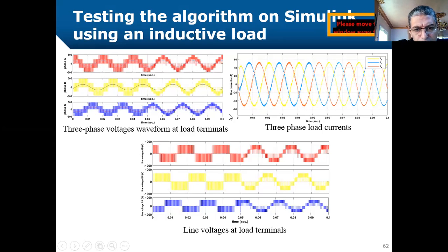second, or 0.005 second, we drive it in 3-level mode. You can see even from this voltage waveform per phase, that this is 2-level. Here, 2-level. Here we can find 3-level, 1, 2, 3 levels. And of course, as we expected, in the 2-level, the current has more harmonic content, and for the 3-level, the current is smoother with less harmonic distortion.